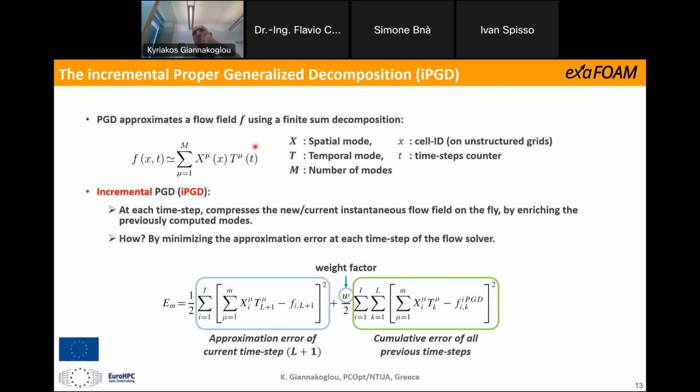PGD pre-existed, of course. We have not developed PGD, but what we developed was the IPGD, the incremental PGD method. In its incremental form, the instantaneous flow fields are all compressed at the end of each time step by updating the already available modes. At the same time, the memory holding the instantaneous flow fields can be freed. This is the idea.